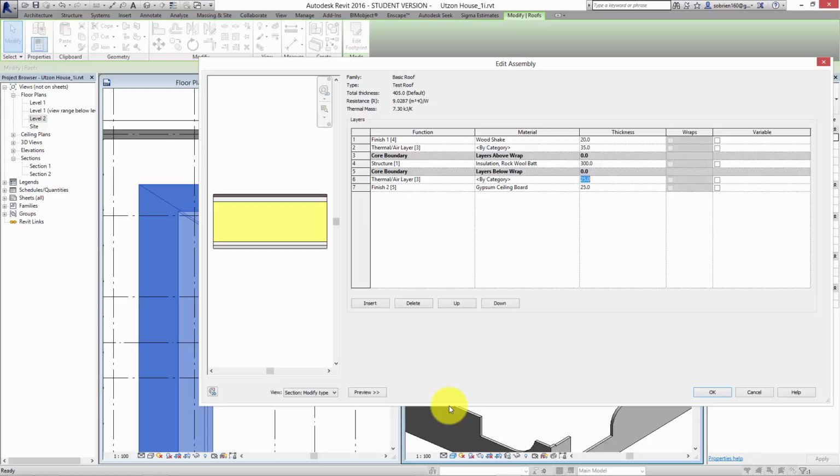And you can see, so now we've got the structure of the roof set up. All the way from the outside, the air gap, the insulation, another air gap, and the gypsum board inside. Notice that we don't add any of the timber structure in here. We leave the structure out completely because we're just setting up the layering of the roof. We're not worrying about how all these things are held together yet. We're just really concerned about the overall layering of the roof. I won't get onto structure till later on.